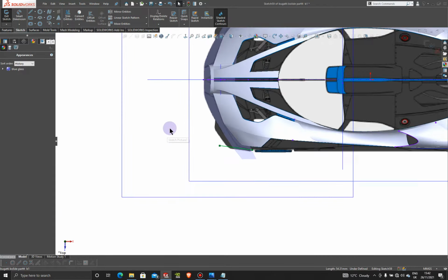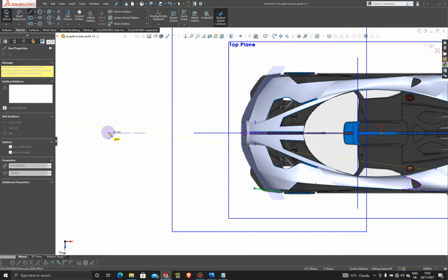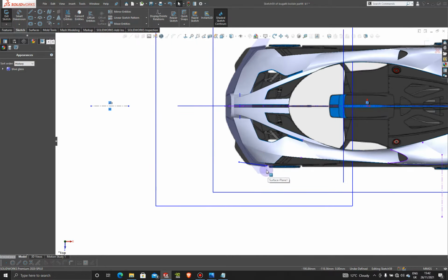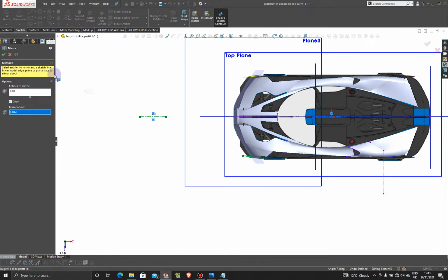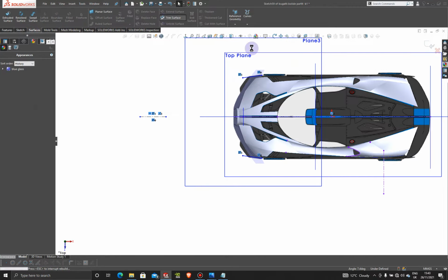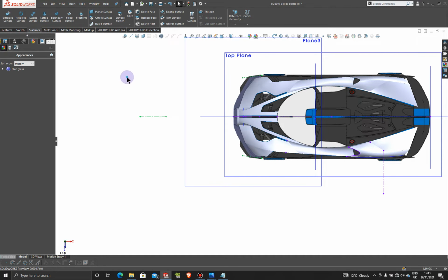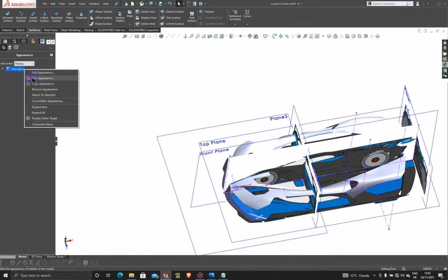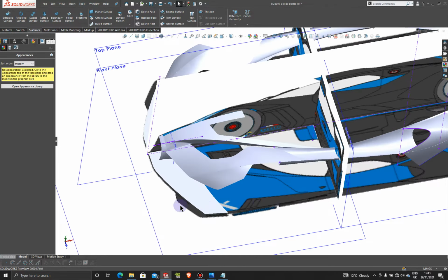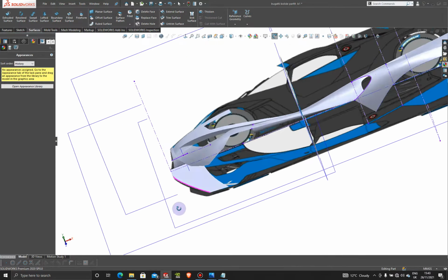Okay, and of course we need a center line, a construction line here, with just one. Make that nice and straight. Exit the sketch, and then a mirror entity is going to be this entity mirrored about here, and the surface tool, trim surface, and let's trim these two surfaces here. All right, so let's remove that glass appearance. Okay, so we have that removed.